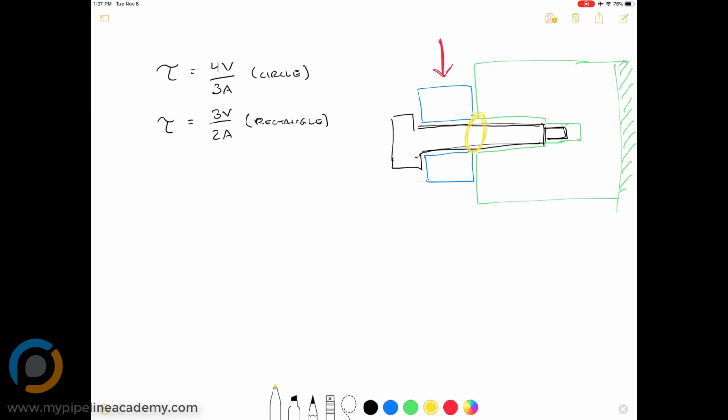Because the end of the bolt is supported by the green part down here, the bolt is being pushed down into this area. And the far half of the bolt is being pushed down and supported by this area. So really, this green part is pushing back up on the shoulder screw in this area here, and the blue part is pushing down on the shoulder in this area, and that creates a situation called shear. This is the definition of shear, where you have forces acting in opposition to one another that are adjacent to one another as well. So this is a shear example.